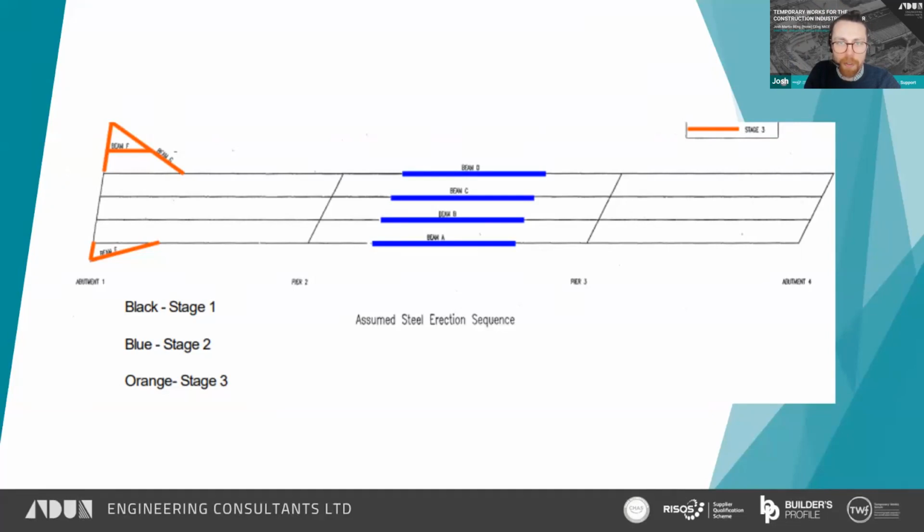So this approach confirms that the bridge will remain stable throughout the demolition works, including when the free end is separated from the fixed end when the blue structure in the centre had been removed. There can be significant risks associated with latent defects in structures, a latent defect being a fault in a structure that could not have reasonably been discovered through inspection. So therefore, by following a reverse sequence of the construction sequence, we can be confident that the stability is ensured.